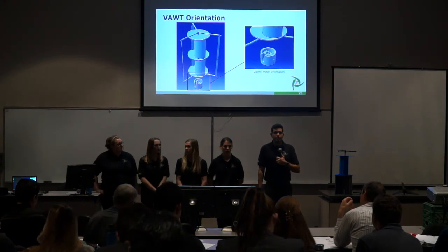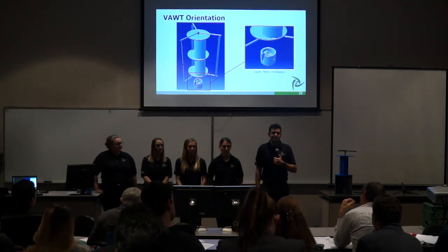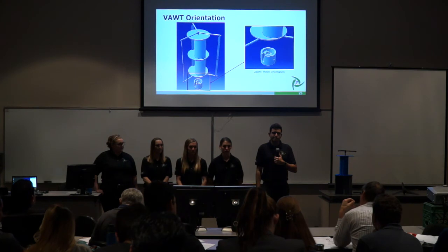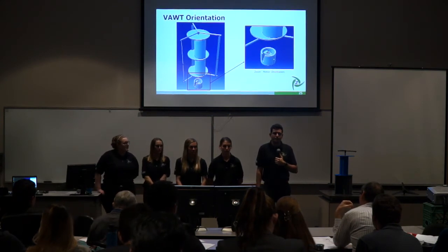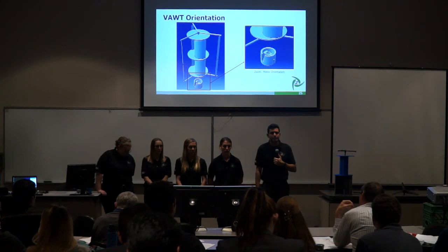The buck converter? Buck converter, yes. Is it, so it'll protect the user's equipment against any type of voltage? Yes, so it has a fixed 5-volt output, and we have to go into more testing to ensure that it does give us the 10-watt output that we require.